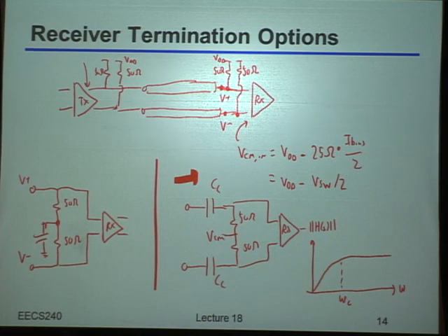And so remember, the capacitor at DC has infinite impedance. So that means that at DC, indeed, the common mode would be lower than it was before. I'm just adding this capacitor in so that at any quote-unquote reasonable frequency, I still have a good common mode termination. Meaning that I don't have an infinite impedance looking into it from a common mode standpoint. Okay, great. Other questions?